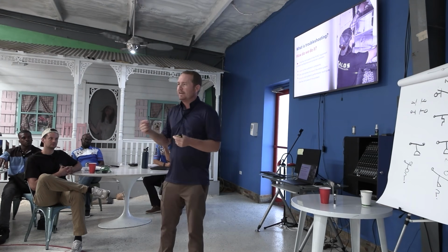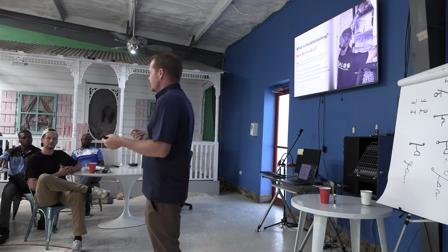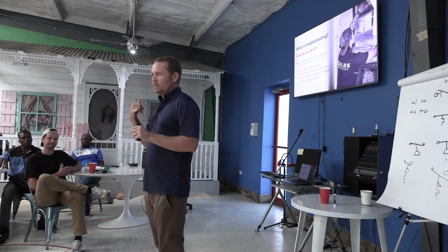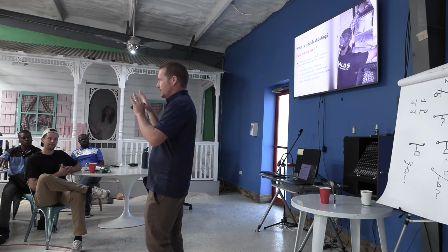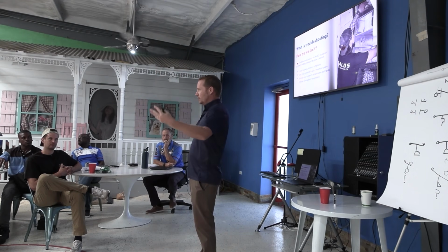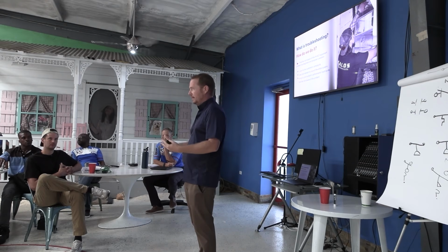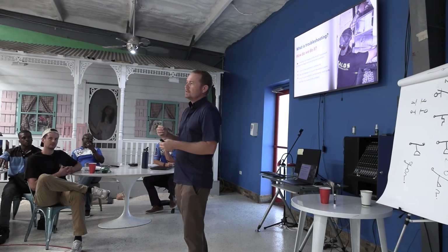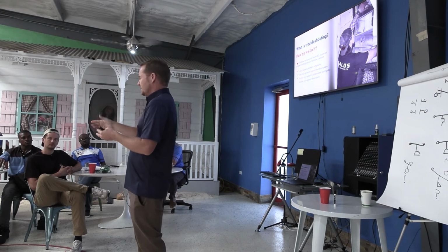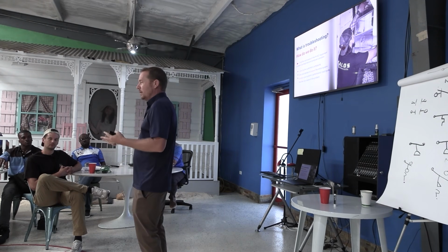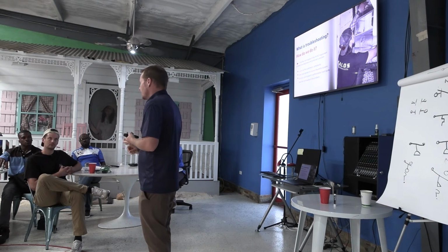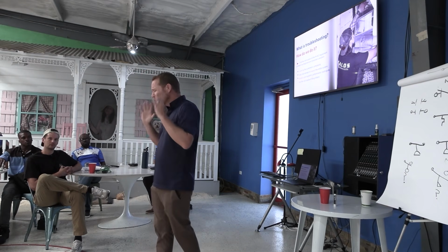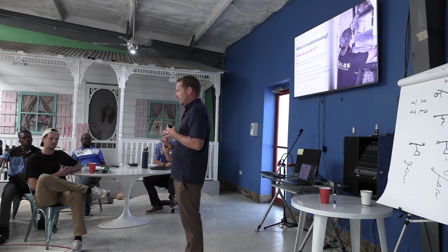You're not second guessing yourself every time, all the time, right? You're following the process, then all of a sudden it's like, hold on. This doesn't match. I'm not going to call somebody right now because what I'm about to give them, I understand, is a senseless pile of goop, right? So I'm going to try to establish, all right, am I actually connecting to the Schrader here? Is it actually pushing in? And that's where understanding your tools matters, and that's why I always go back to when we talked about your vacuum pump and your leak detector and your multimeter, and those tools that you have to use all the time, your probes, your gauges. You really, really need to understand those tools. You need to understand the care and maintenance of those tools.